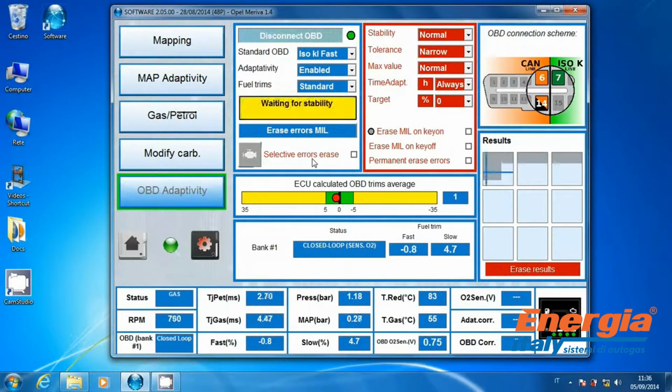Obviously this is done automatically by the ECU and only while we are driving on gas. We usually provide a little set of error codes that are the target of this feature, even if some software customization has its own. However, the selected error codes we put inside are usually false positive errors. I mean conditions that are detected as errors by the petrol ECU while we are on gas, but we know for sure are not errors at all. However, let's have a try.